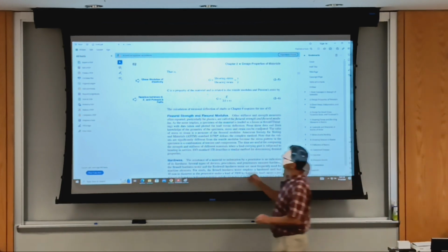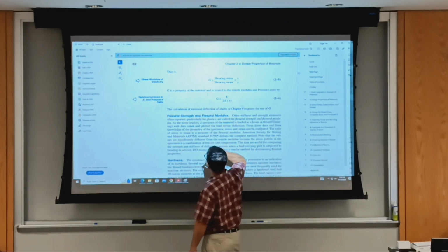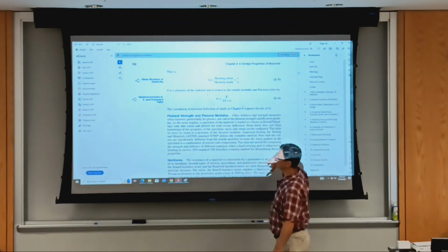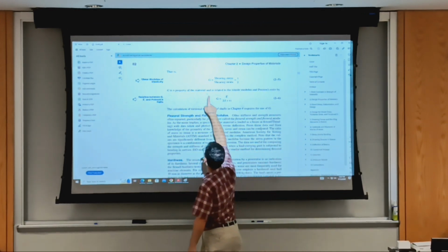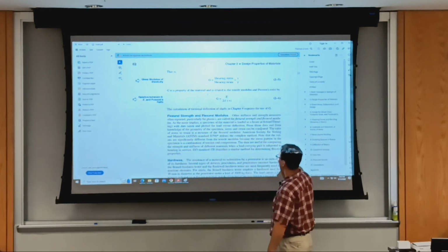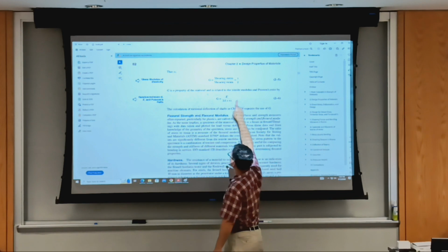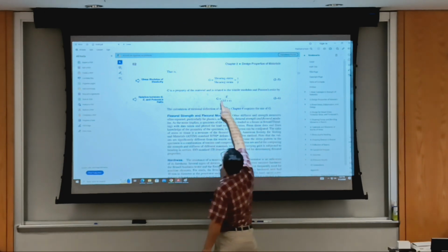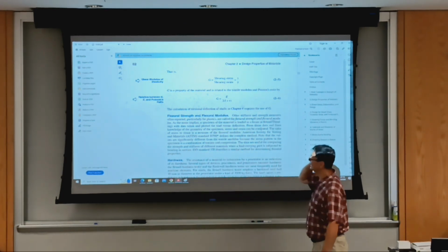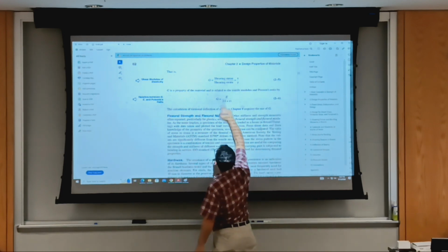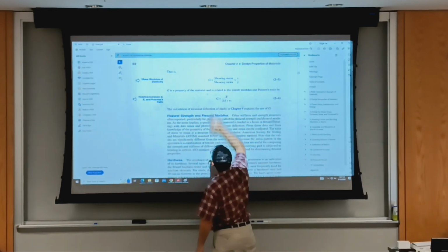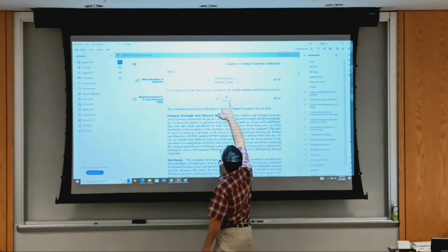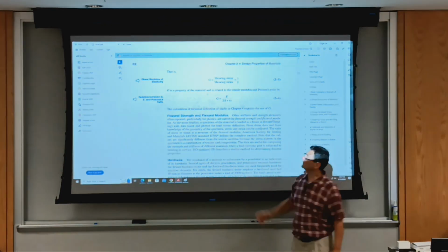The proportional coefficient for that kind of test in twisting is the shear modulus of elasticity, or modulus of elasticity in shear, noted G. You can see there shearing stress over shearing strain. And shearing strain is in radians, which are assumed unitless. So both E and G have units of megapascals, PSI or KSI, and they are related via the Poisson ratio. So if you have modulus of elasticity in tension, which is the most commonly available one, and you know it's steel and the Poisson ratio should be around 0.3, you can get an approximation.